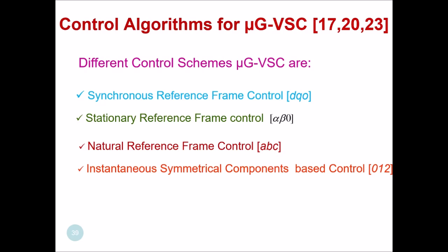So the idea is that when you want to do something with the help of microgrid, we must know what amount of quantity is required to be injected or to be generated, either in a current form or in a voltage form. If the microgrid is in the grid interactive mode, then we have to generate the reference quantity in current form.